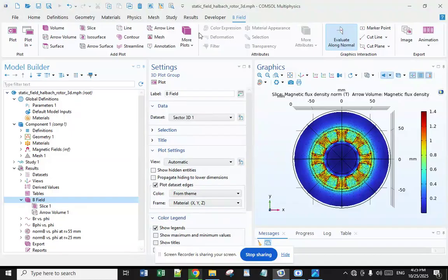The next is linear array magnetization. The magnetic flux distribution of a linear Halbach array may seem somewhat counterintuitive to those familiar with simple magnets or solenoids. The reason for this flux distribution can be visualized using Mallinson's original diagram. Note that it uses the negative Y component, unlike the diagram in Mallinson's article.